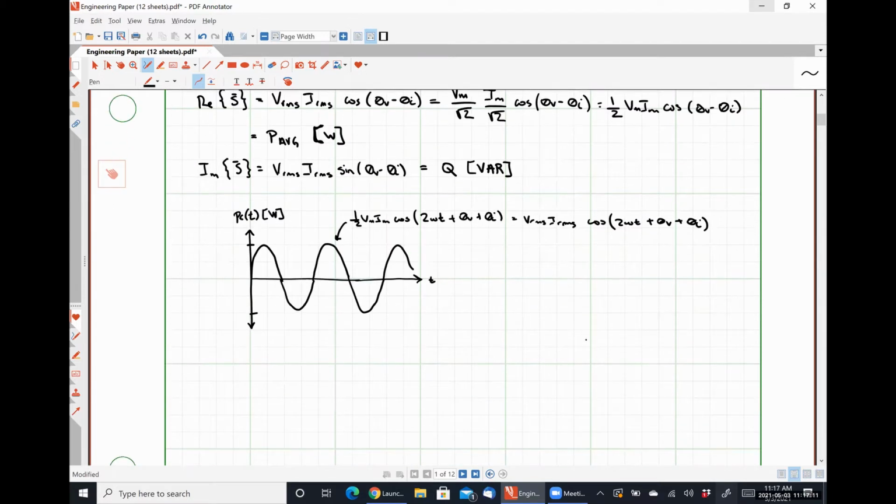If we look at the magnitude of the polar form of the complex power, we simply have VRMS times IRMS, and we call this the apparent power, okay? So that's S with no bar across it because it just represents a scalar quantity. We might also see it represented, some people just do AP for apparent power, and it is measured in volt amperes as well. Apparent power represents the total power absorbed by a load without considering phase differences between the voltage and current waveforms,